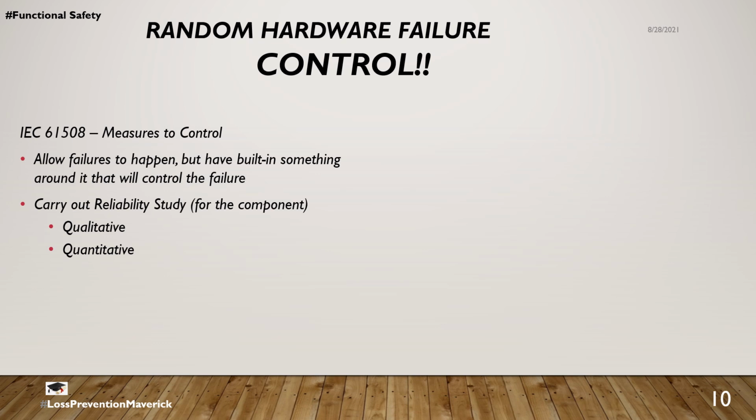reliability assessments qualitatively and quantitatively for the component, for example qualitative assessments like FMECA, a failure mode effect analysis. We will talk more about it when we come to the series on hazard analysis on functional safety, which may possibly be our part 3. Qualitatively, the manufacturers look into what are the various failure modes that a particular component can have, what are its effects, and how can that be controlled and prioritized. And quantitatively as well, such assessments have to be done.